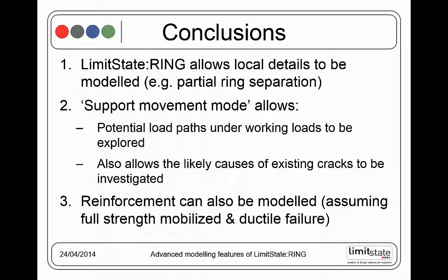Perhaps just say a caveat on that. Personally, I think it's often much more fruitful to look at providing, for example, a mid-surface slab in the fill material as a way of reinforcing a bridge rather than actually reinforcing the arch barrel.